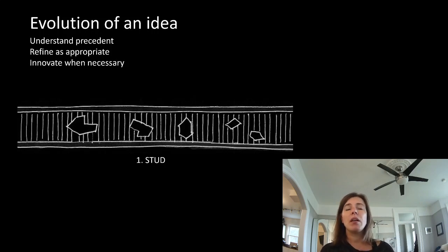Precedent would be, you go in, you put in your studs. So this is talking about not wood studs, but light gauge steel studs. Between your floors, you could follow the outline exactly that you needed, and you just frame around your window openings, and then you could put your window in. The problem with that, like I said, is that we had a 450 millimeter offset, approximately, and our windows were very heavy.